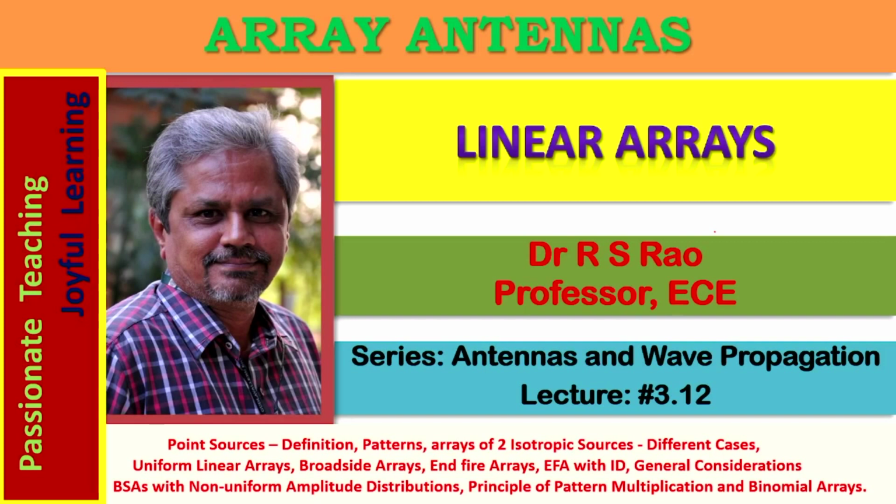Different modes of operation are possible with the linear arrays. Broadside mode and end fire mode are the most important modes. Linear arrays may also be associated with grating lobes, which represent power wastage.